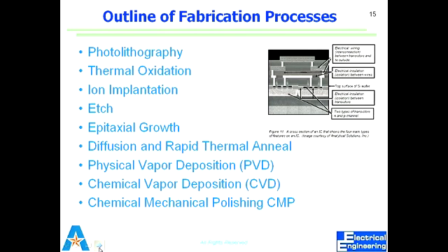Oxidation we do mostly by thermal process. Implantation or diffusion. Diffusions are done to introduce impurities, right? Impurities for semiconductors are good if we know what we are using as impurity, right? We deposit material by PVD or CVD. They'll become easy as we go along, so you'll remember what PVD or CVD is. For me, once you do it too long, you just take it for granted. We'll look at those closely.